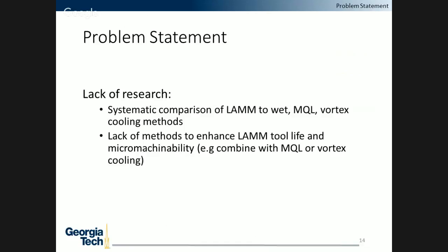A more thorough literature review of all laser-assisted micromilling studies is provided in my thesis. But where current LAM work is lacking is this: laser-assisted micromilling is often presented as an alternative to conventional cutting techniques, but in all studies it has only been compared to dry, which is by far the worst cutting case. It has yet to be compared to other conventional techniques such as wet, MQL, or vortex cooling, which are often used in machine shops to improve micro machinability. That systematic comparison is lacking.